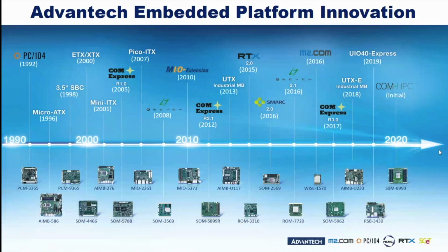For example, PC104, though still available, has many different iterations like PC104, PCI104, PC104 Plus, and PCIe 104. PCIe 104 has never actually taken off. The reason is that the connectors are not as rigid as the previous generation. ETX and XTX were around during the time when there was the ISA signal, so now they are more or less phased out.